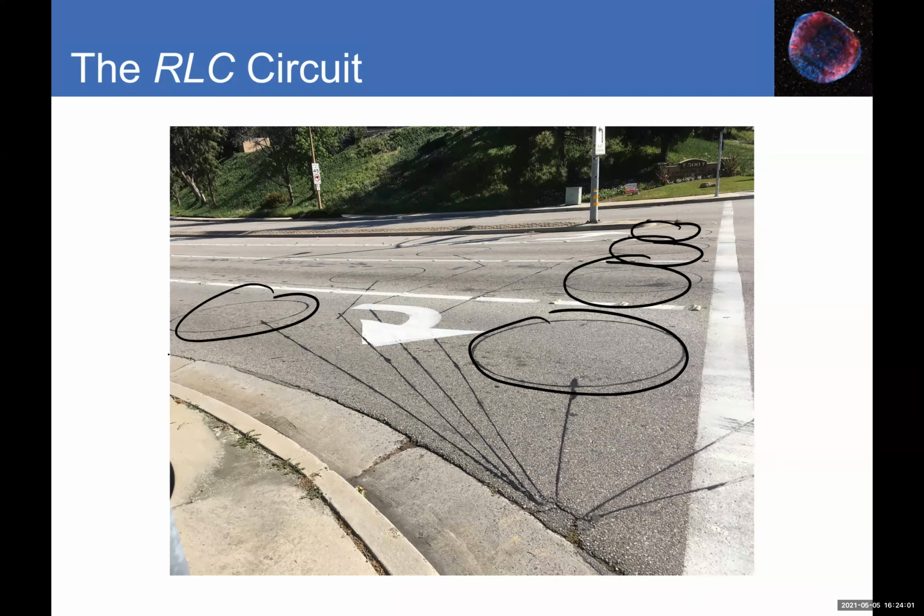When your car approaches, that's a moving conductor. The metal of the car represents a magnetic material, and that alters the magnetic field passing through the loop. Then eddy currents are induced in the metal of the car, producing additional magnetic field lines. That means the moving conductor, as we learned especially in motional EMF, can induce current and EMF in those coils under the street.